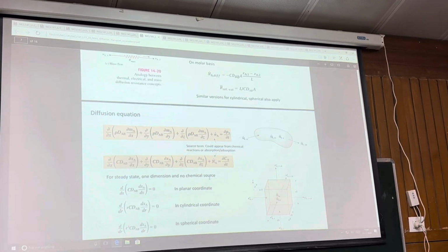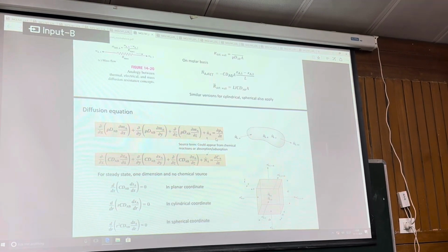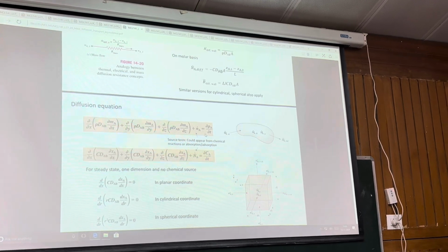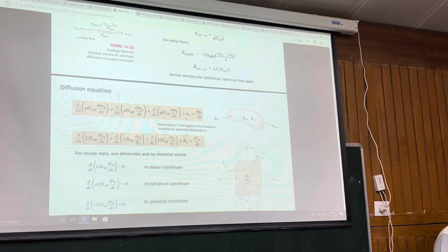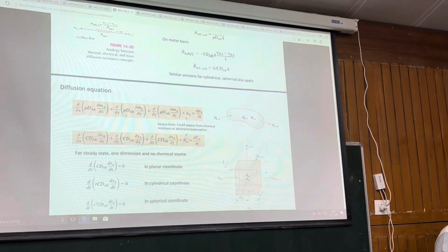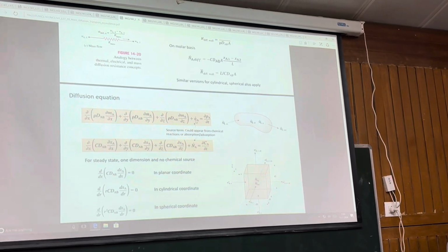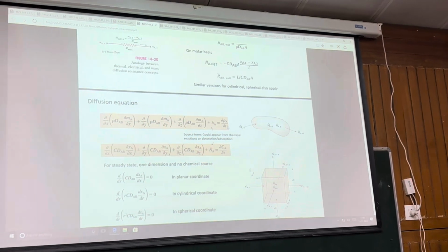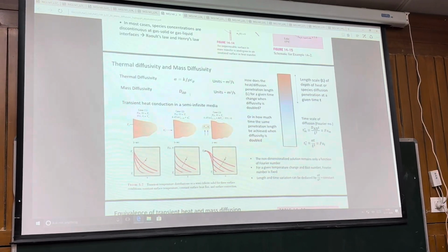Mostly in 1D. So all these problems will be in 1D. Mass diffusion, everything will be one-dimensional, not two-dimensional. Even the heat conduction also one-dimensional, nothing two-dimensional. So you can write one-dimensional forms of these equations. In the one-dimensional form, this y term and z term you get rid of, and only x term and production term and change with time, this term you can keep. This we have done today.